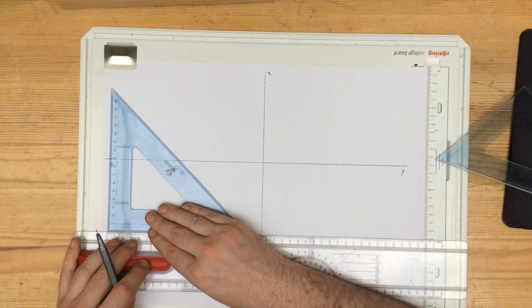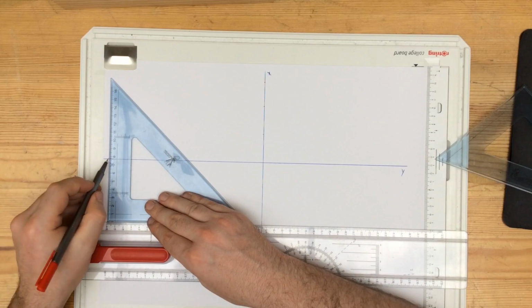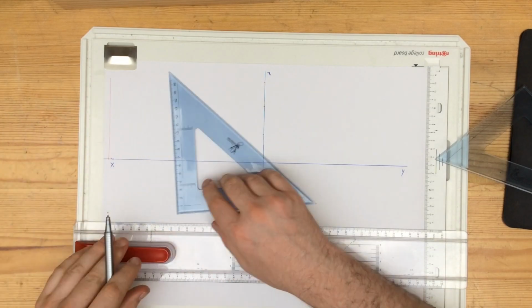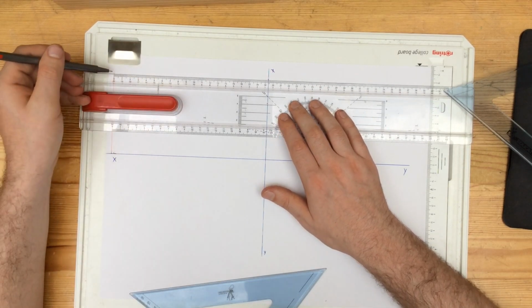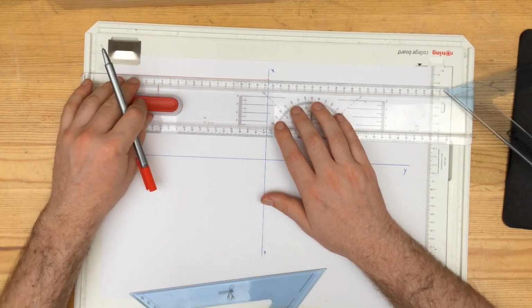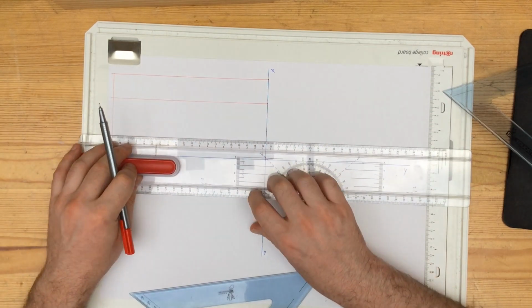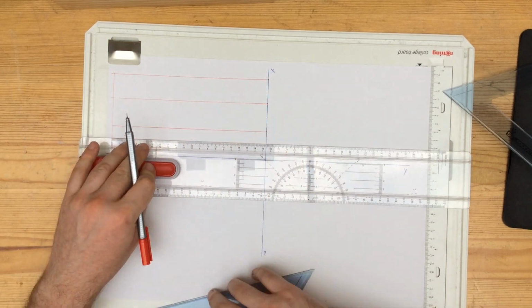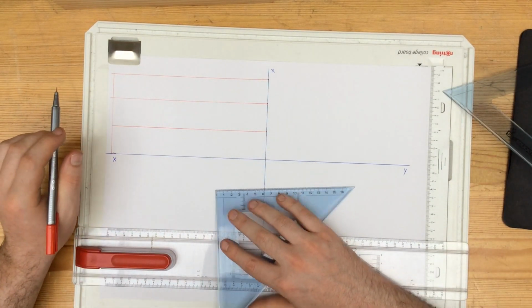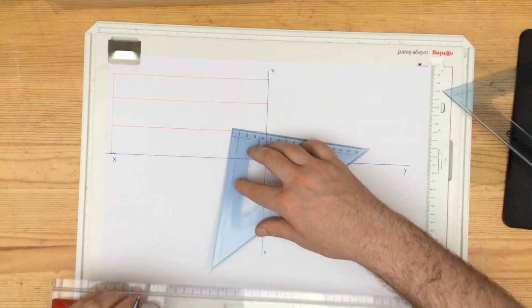With the widest point established and the highest point established, I am now going to use construction lines, which in this case is a red colour, to complete the overall size of my elevation. This allows me to know that everything else for the elevation for this particular drawing must fit inside that rectangle shape.